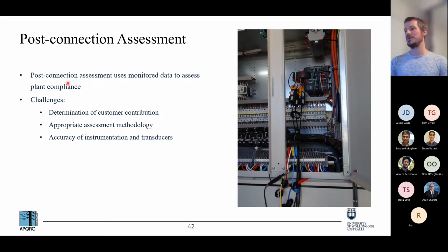difficult. Also, there are difficulties with the state of the network that actually impacts the capability of a generator to actually meet its compliance. It ultimately shows that if the network is not in the state that you expect it to be when you allocate and perform pre-connection compliance assessment, the generator is very unlikely to actually meet compliance. So whose fault is that? Is it a problem? If voltage levels aren't out of control, then no, it's not a problem.